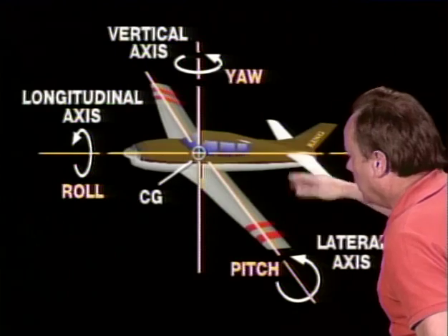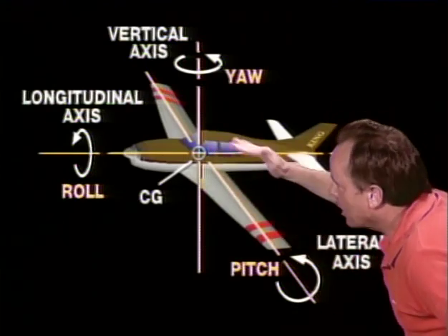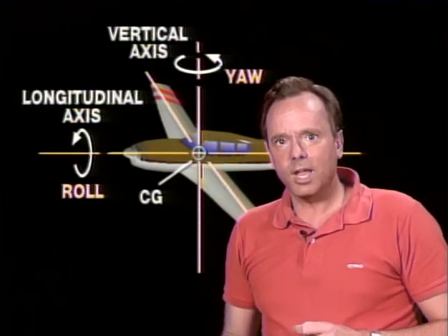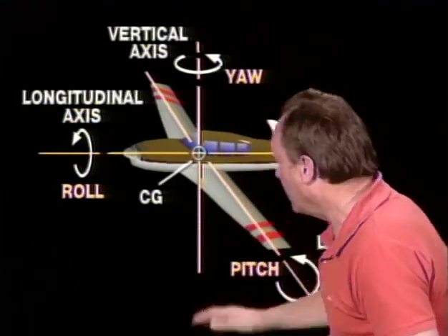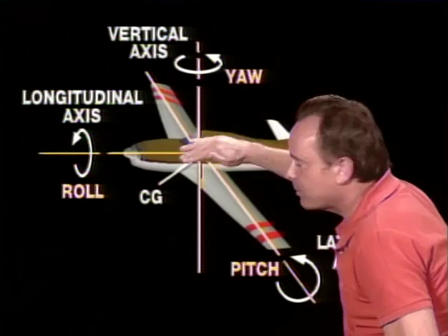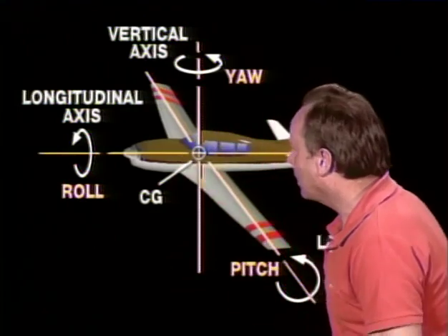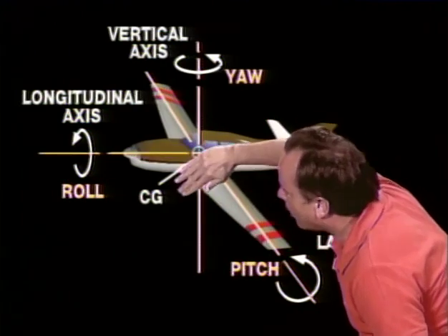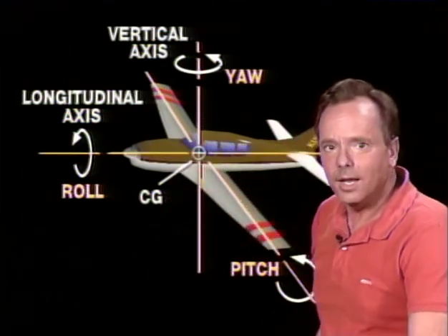So the lateral axis is what the airplane pitches about, and that's what improper rigging of the elevator trim tab system would affect: the balance of the airplane about its lateral axis. Now, if they talked about along the longitudinal axis, they'd be talking about along this line, but it's about the lateral axis. Now let's talk about wing twist and washing in and out of wings,